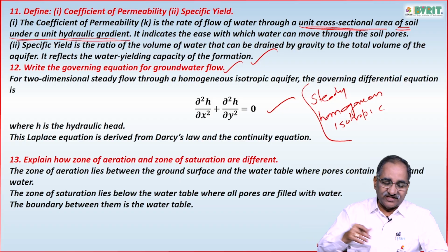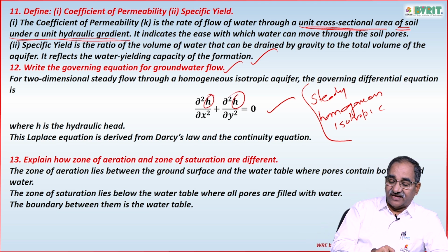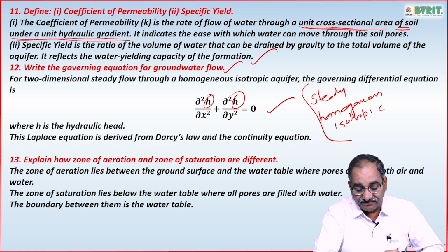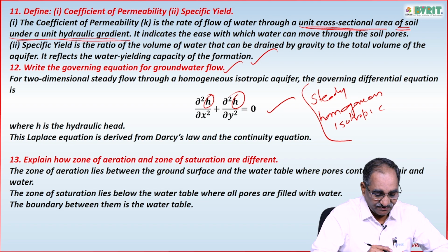For unsteady flow, it is different. What is this h? It is nothing but the hydraulic head. And this equation is called the Laplace equation, and it is derived from Darcy's law and the continuity equation.